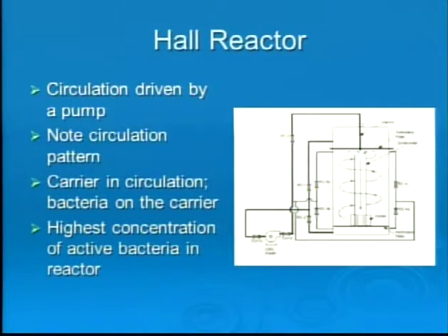Also, as the bacteria produce nitrogen gas, the little croutons want to go to the top of the reactor. They're trapped between porous plates in the reactor, and we force them back down the center tube. So we're continuously cleaning the reactor and the sponges and keeping them in a high concentration.